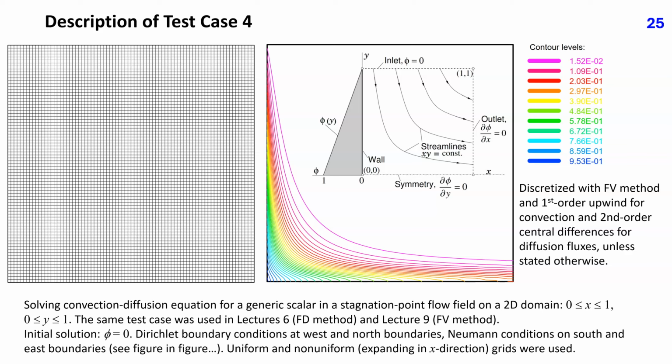When central difference approximations are used for both convection and diffusion, deferred correction or under relaxation is required because otherwise some solvers will not converge. To avoid such problems, tests were first conducted on all grids using first-order upwind scheme for convection and central differences for diffusion. Central differences for both convection and diffusion are tested on the finest grid only. In this case, ICCG solver cannot be used because the matrix is non-symmetric. CG stub solver is used instead.